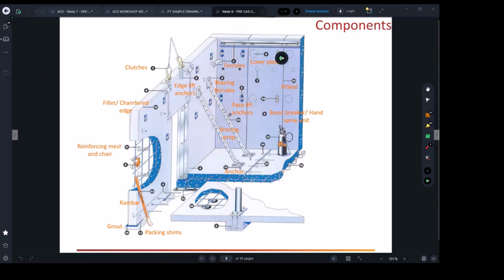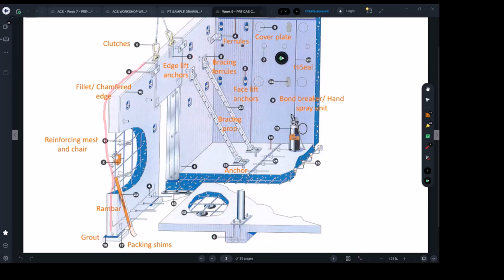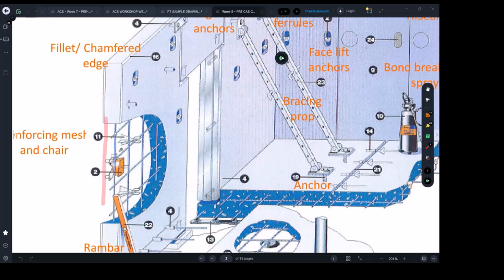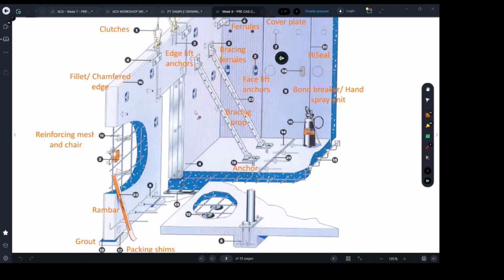I've also mentioned to you that these walls that you see here can be built in situ, no issues. But again, that will be slow and reduce the speed of construction, because if we need to build those in situ, then we first need to place the reinforcement, which can be single layer or double layer. Then we need to put in formwork, pour the concrete, vibrate the concrete, and cure it. It's time, it's cost.